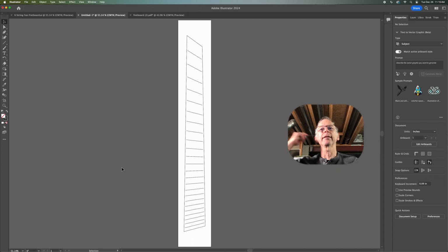And the reason for that is some of the parts that I'll be cutting are going to be two-sided carving operations. And I want to make sure that they're centered in the blank so that when I flip the blank on the CNC machine, everything registers and lines up. I hope that makes sense. Once you've done this a few times, it all starts to click.